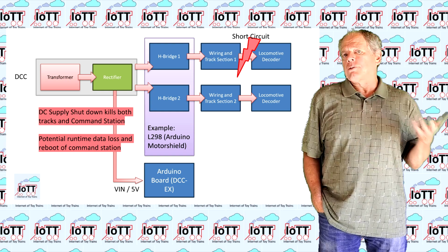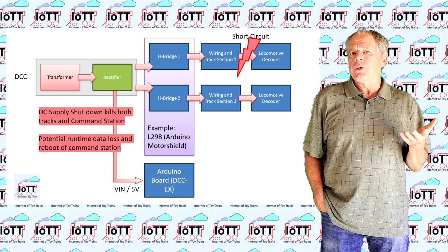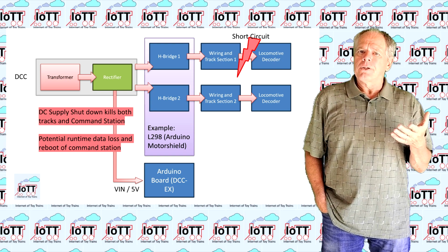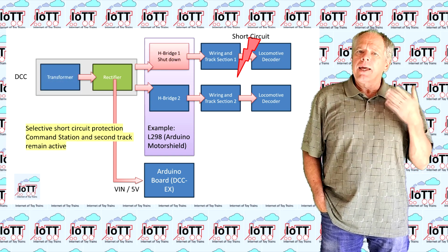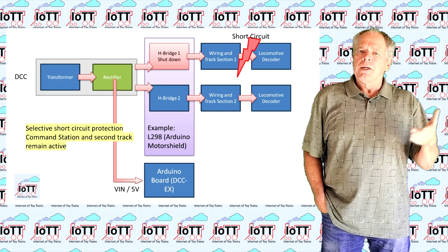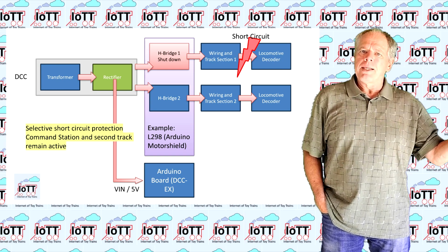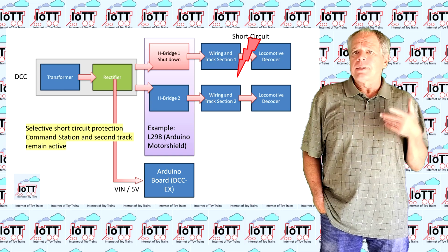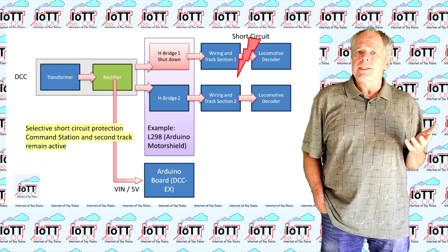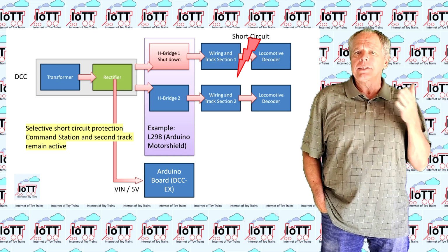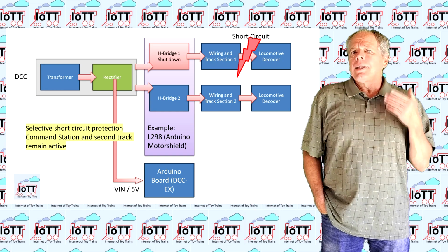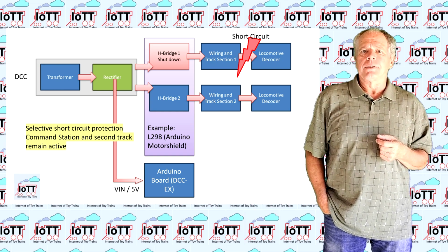If you are using one of these configurations, it is therefore extremely important that the available short circuit current of the DC power supply can exceed the trip current for the entire 100 millisecond interval. My concern was in particular that this might not always be the case if the DC power supply is heavily loaded at the time the short circuit occurs, and that's what I tried to find out.